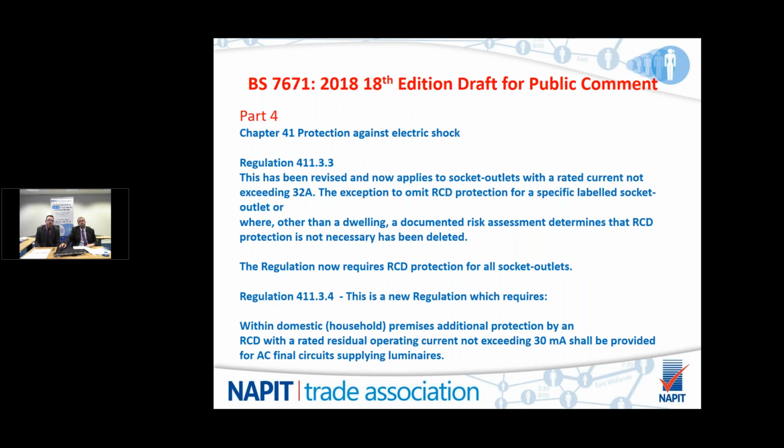Also within Chapter 41, Protection Against Electric Shock, is Regulation 411.3.3, which applies to socket outlets and RCD protection. Previously, the regulation stated that socket outlets with a rated current not exceeding 20 amps had to have RCD protection. This has now been changed to 32 amps, so it has increased the rating of the socket outlets that have to be covered by RCD protection.